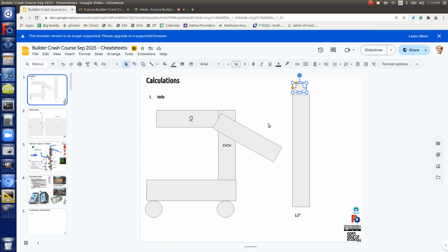If the roof is rated 50 PSF, that's the rating we have on the roof right now for the trusses, 50 pounds over 720 square feet, the max load we need to hold is, holy cow, close to 50,000 pounds, let's say. You're spread over a lot of the walls, but say a couple of thousand pounds each wall needs to hold. It's 5.5 inch.